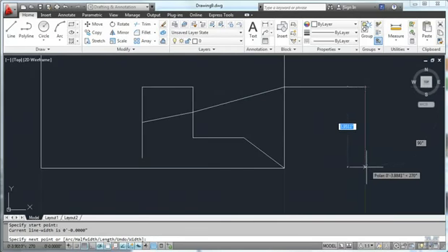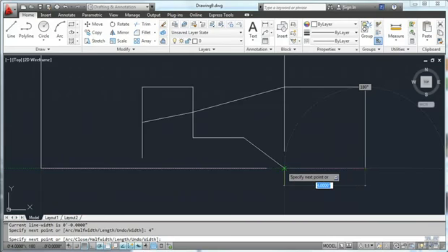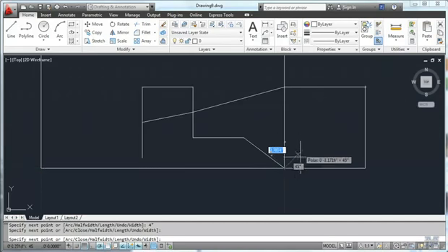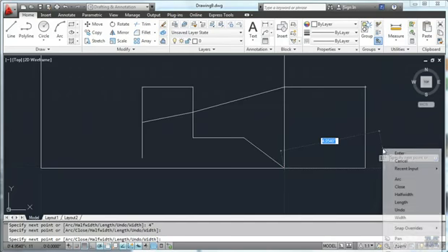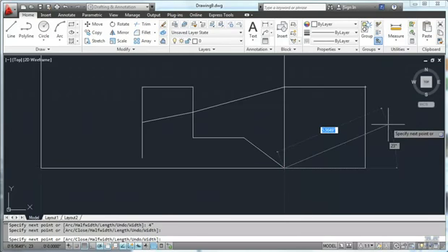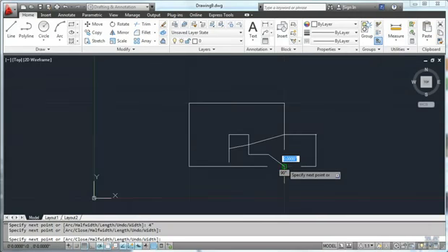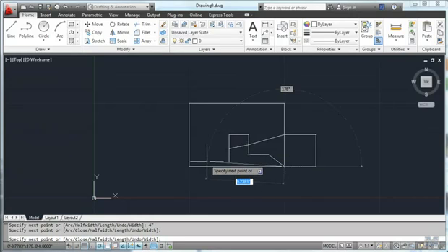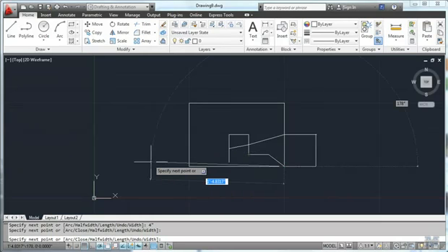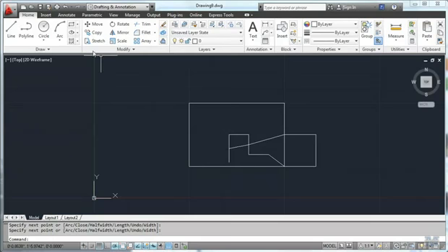So just to check, if we went down 4 inches, I'll just type 4 inches, and then over 4 inches, yep, that lines right up. That was 4 by 4 away from it. Now one thing you've got to be careful about, hit the right mouse button, is absolute reference. In this case, you want to use a relative reference, which if you recall, you have to use the at symbol for relative, the pound symbol for absolute. So let's get out of this and try that.